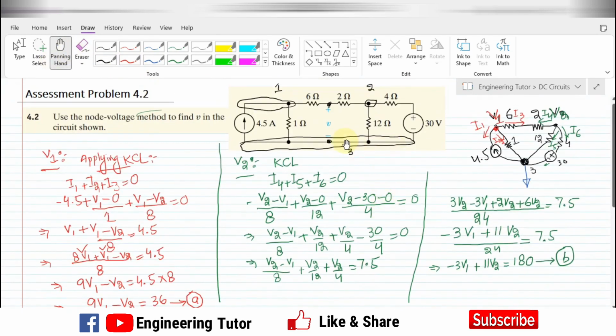So now in order to find the value of this voltage V, we can see that the voltage here is the voltage at this point minus the voltage which is dropped across this 2 ohm resistor. So in order to find the voltage drop across this 2 ohm resistor, we have to find out the value of the current flowing across it. Let me call it I1.